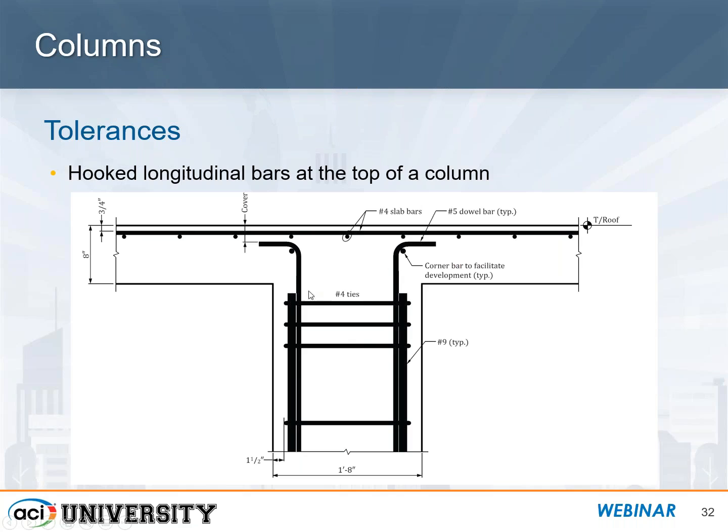You want to make sure that you've got enough confinement here where it's transferred. And I would consider it like a sloping bar where you splice the longitudinal bars in the column. I know that has a horizontal kick to it from the bar being offset, but if you think of it in a similar fashion, that's a recommendation we have for this type of detail.